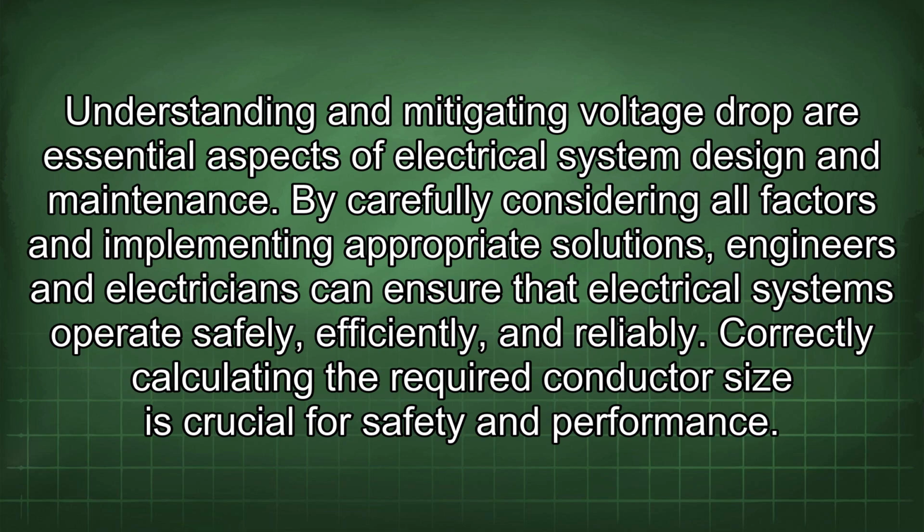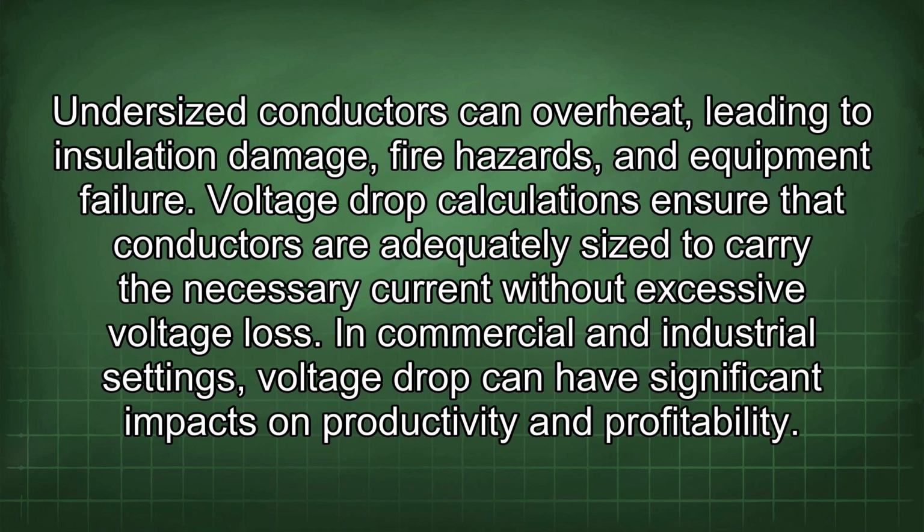By carefully considering all factors and implementing appropriate solutions, engineers and electricians can ensure that electrical systems operate safely, efficiently, and reliably. Correctly calculating the required conductor size is crucial for safety and performance. Undersized conductors can overheat, leading to insulation damage, fire hazards, and equipment failure. Voltage drop calculations ensure that conductors are adequately sized to carry the necessary current without excessive voltage loss.